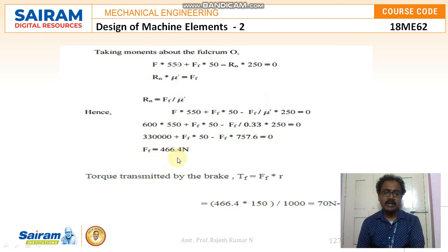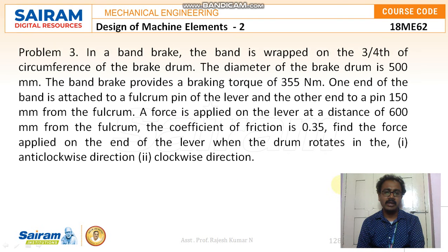From this I can find the Ff value as 466.4 Newton. And the torque transmitted by the brake, Tf, is equal to Ff into R. So the value I am getting is 70 Newton meter, or 17 into 10 power 3 Newton mm.